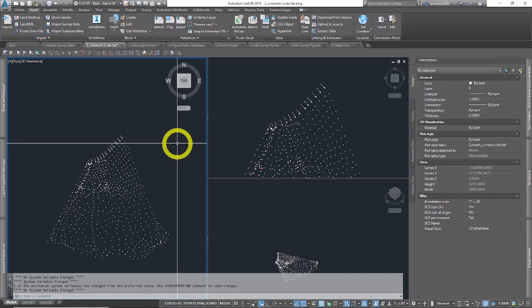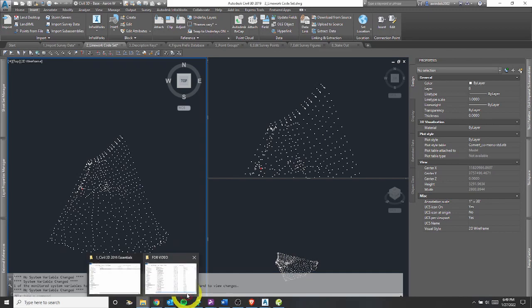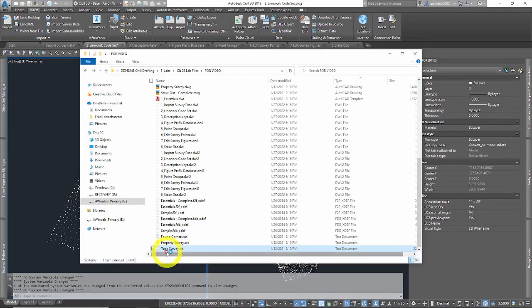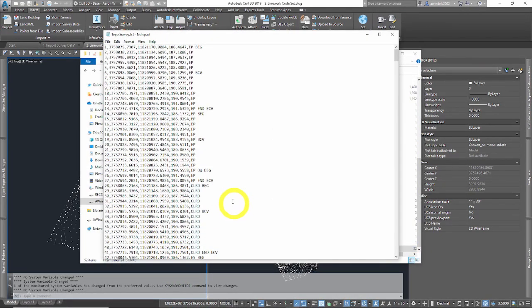Now, to look at some of the codes a little bit, some of these have further descriptors on them. This is the raw description code that says maybe edge of pavement, and it has a further code. There are different terms for this, but it's an appending code or an additional line work code that might have a numeric code to distinguish this edge of pavement from another edge of pavement, called a numeric sequencing code or a numeric identifier.